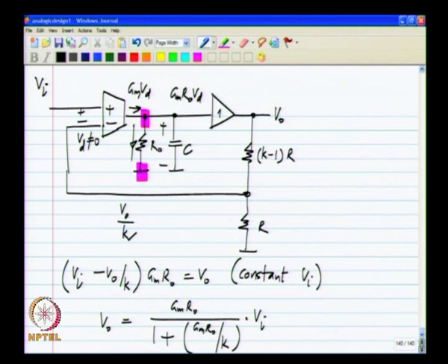And we can see that in the limiting case where Ro goes to infinity, this is k times Vi when Ro is infinity. It passes the sanity check: whatever case we had originally with the ideal voltage controlled current source, this satisfies that one, that corresponds to Ro equals infinity. So, when Ro is less than infinity, this number will be smaller than k.